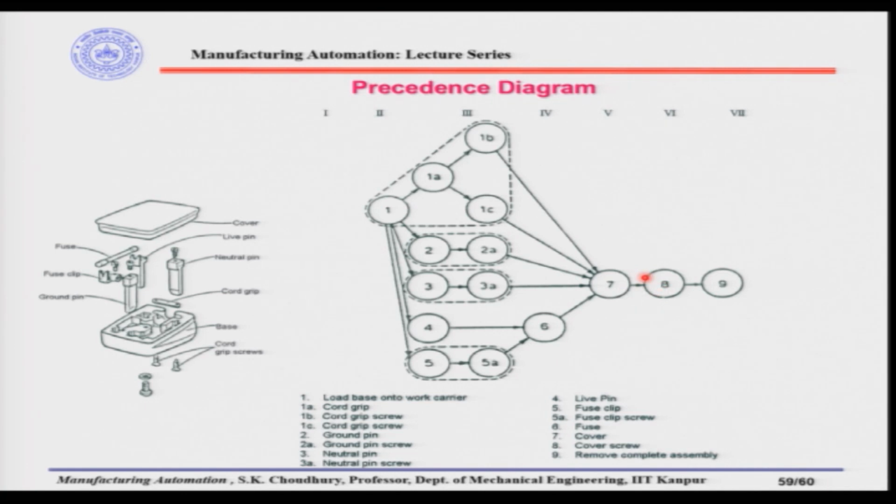There is one point here in the assembly process: if the assembly is very big, meaning that there are a lot of parts to assemble, then, to avoid having a large number of assembly workheads and assembly machines, many times the assemblies are broken into small sub assemblies, and the sub assemblies are made in a line.